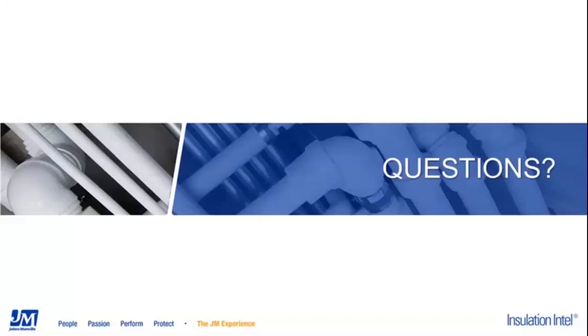So what I think would be important to consider is the relative humidity it's going to be installed in. Fiberglass can certainly be used on chilled water applications, but if the application is in a really, really high humidity environment, Trymer PIR might be a better option because, again, it's a closed cell insulation. I'll let Heather tag on to that. Yeah, I think that's a great point.